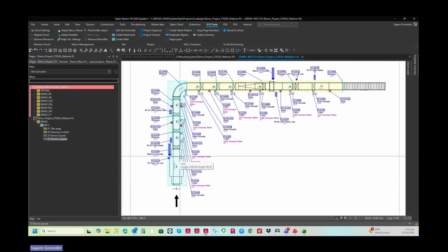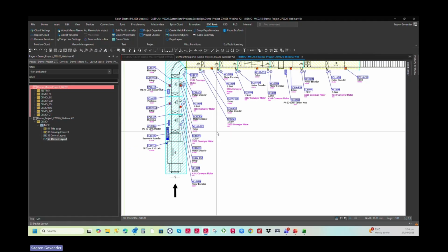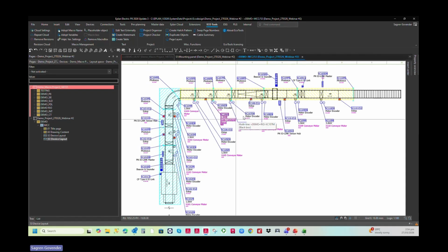And here I've got an X-ray system, and the pallets or bags go along here and end up in this lateral here. So here again, I've got a lot of devices, and some of them are mounted on, so some of them are connected onto the drive. These are all remote I/O, remote devices. I've got some IO-Link modules. Some of the devices are connected to IO-Link. Some of the modules are connected to the drive itself, and the drives are on Profinet, and so forth in here. So there's all of the devices in here.